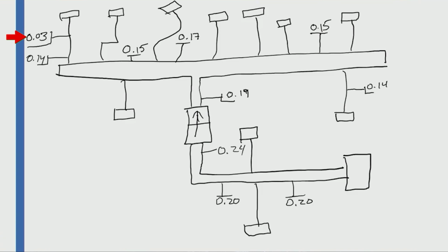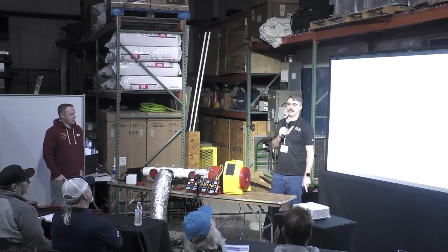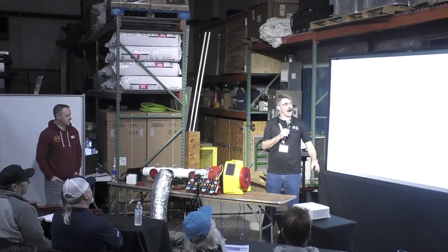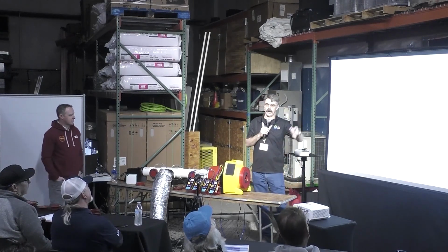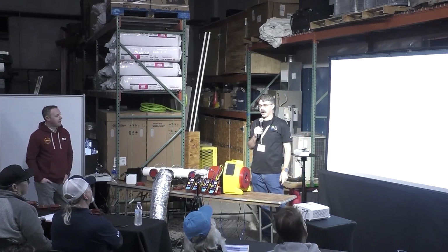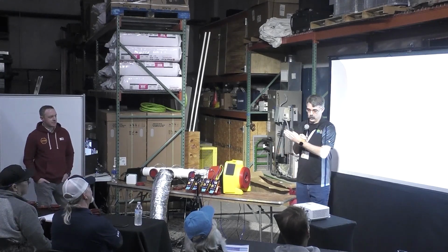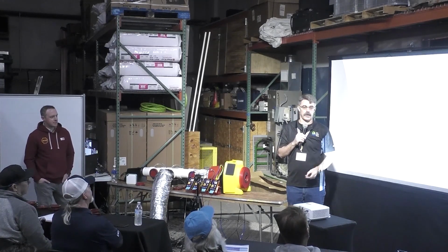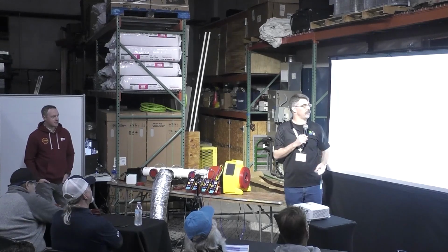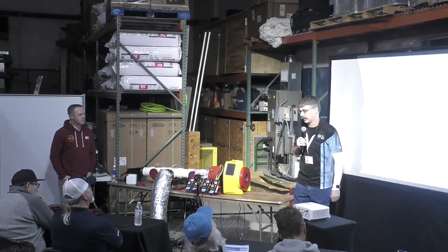Maybe. Or maybe there's a damper that's closed in there that was purposely limiting the airflow to that room. But if that room had a complaint on it that it wasn't staying comfortable all the time, I can then go down that duct, periodically taking pressure readings and figure out exactly where the problem is. Typically in a duct system, you want to see a nice, smooth decrease of static pressure all the way to the end. But if you get a sudden change, a massive change like that, that's a problem inside of the duct typically.